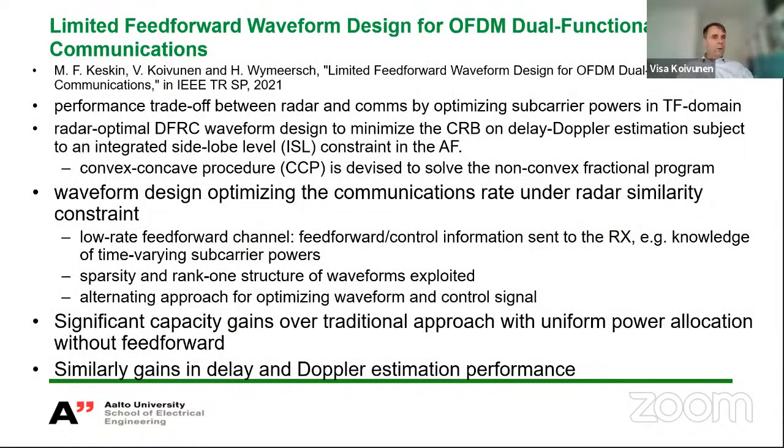Then our more recent work that we did with Furkan Keskin and Henk Wymeersch is limited feed-forward waveform design for these OFDM dual-functional radar communication systems. The idea is to optimize subcarrier powers for both radar and communications in the time-frequency domain. And we will have a radar-optimal design for this dual-function waveform. The idea there is to minimize the Cramér-Rao bound on delay-Doppler estimation, with a constraint on the integrated sidelobe levels of the ambiguity function.